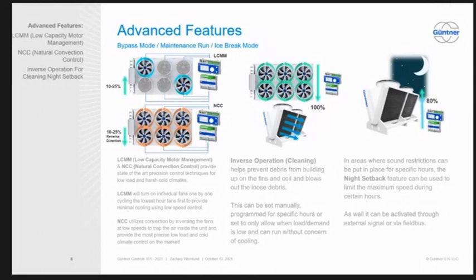I was just curious because I know anytime you have a lot of expansion and contraction on those microchannel, they don't like it. The coils end up leaking. I know Kevin's had a bunch on those A-frame style condenser coils that they have out there. We've had a lot of leaks on gas coolers in general, and I think it's due to the fan control. But what you just showed is a big proponent of stopping that.